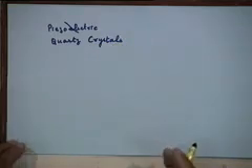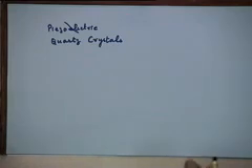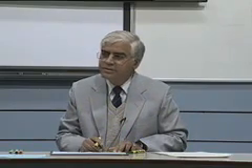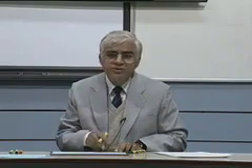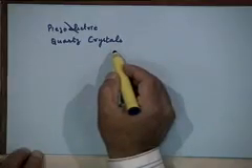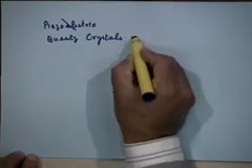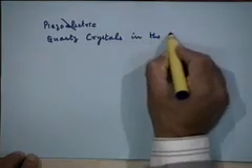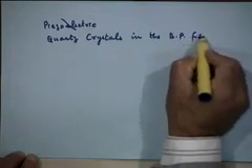And interestingly, they have some very useful electrical characteristics, and they can be used in the resonance circuits of tuned circuits to provide you a very sharp frequency response, right? So you could get the kind of filters that you want to design for the SSB generation by using quartz crystals. So you will use quartz crystals in the band pass filter for sideband filtering.